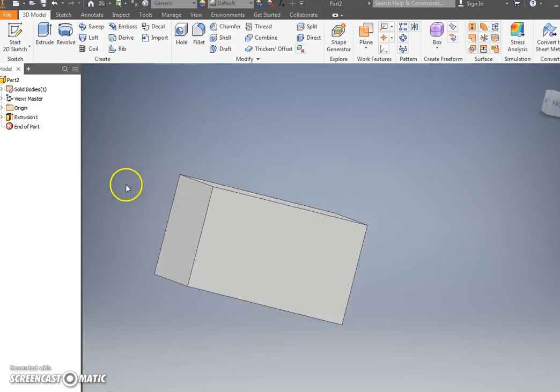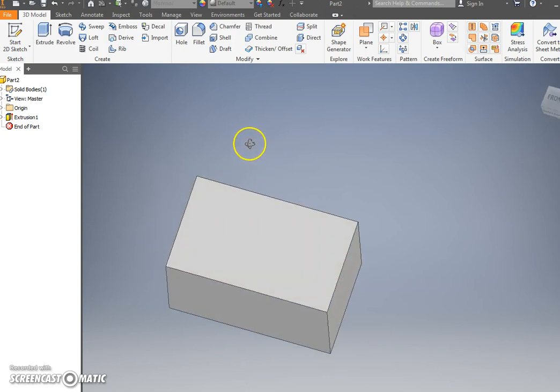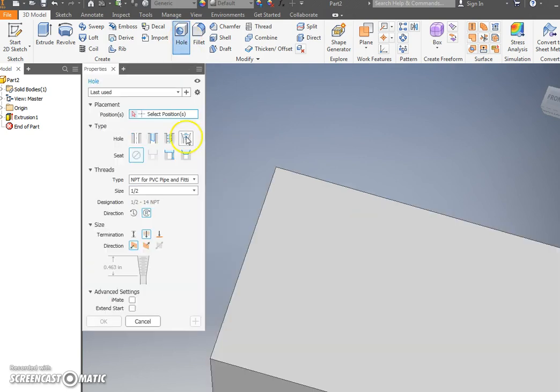So we're going to make some holes next, and we already made one once on a concentric center point. This one's going to be more of a linear one. So on this one, you click on the hole, and then you click somewhere on your block. It doesn't matter where you're at. It's important now when you're doing a countersink to expand out all of these dialog boxes. Yours may not be, so please just go ahead and do so.